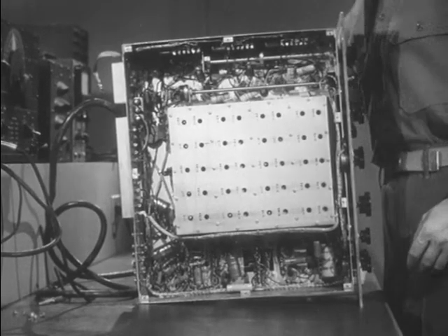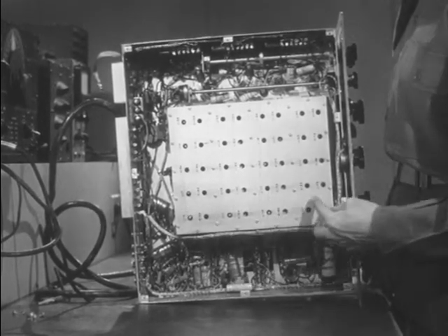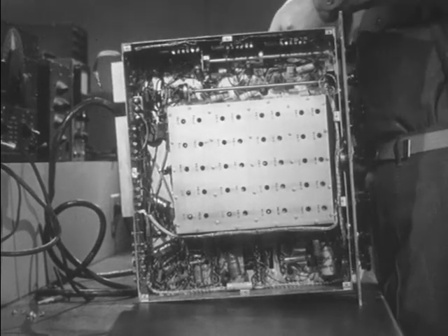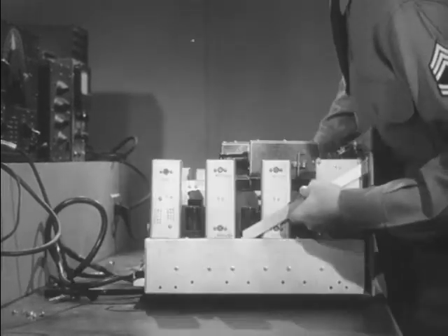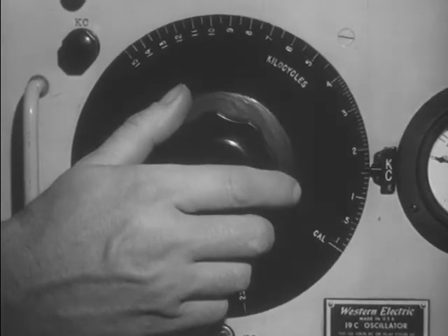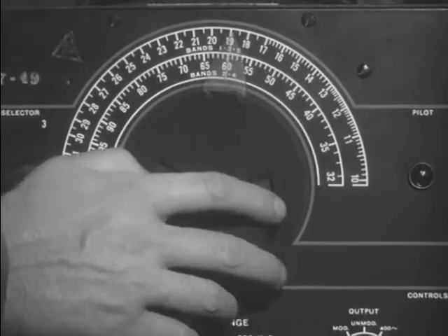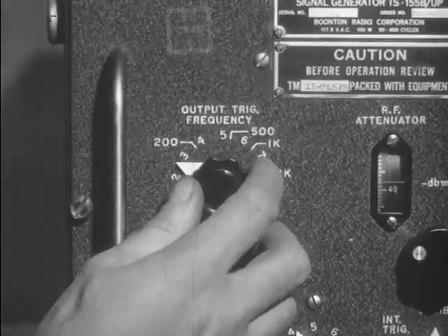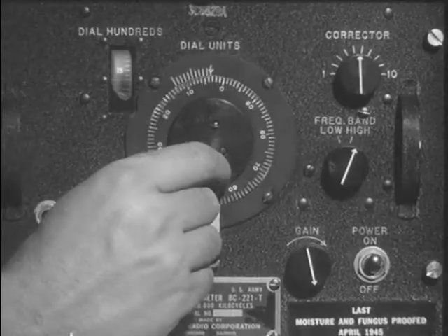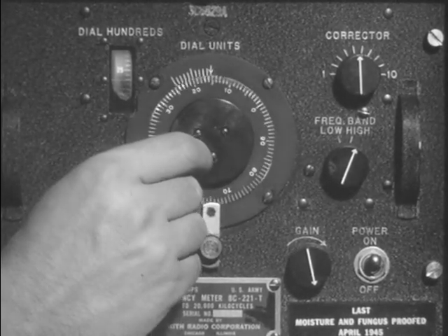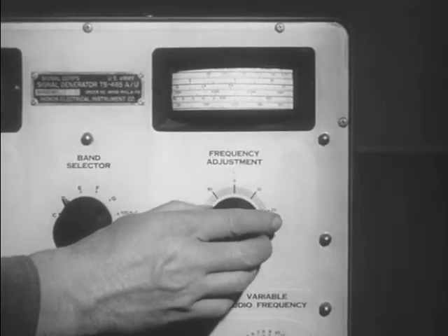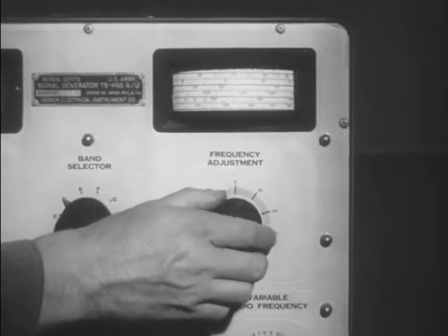The tuned circuits of any receiver must be accurately aligned to operate at maximum efficiency to permit reception of each of the transmitting stations or frequency channels. To test or realign a receiver, signals are needed on several frequencies in order to accurately adjust the circuits of the set. So the signal generator or oscillator is used. The signal generator may be defined as a miniature transmitter, producing a signal of any desired frequency and strength to test radio and other electronic equipment.